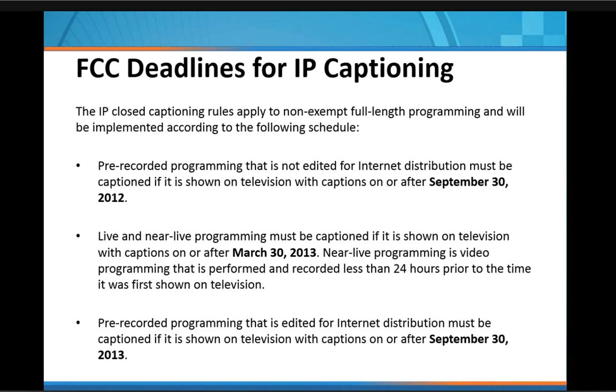Well, line 21 means different things depending on who you ask. As a technical standard, line 21 is where the captions were put in a standard definition video signal. So to a lot of people, the synonym for the closed captioning standard, which is called CEA 608, and I'm going to go into that in a little bit, was line 21 because that's what the engineers called it.